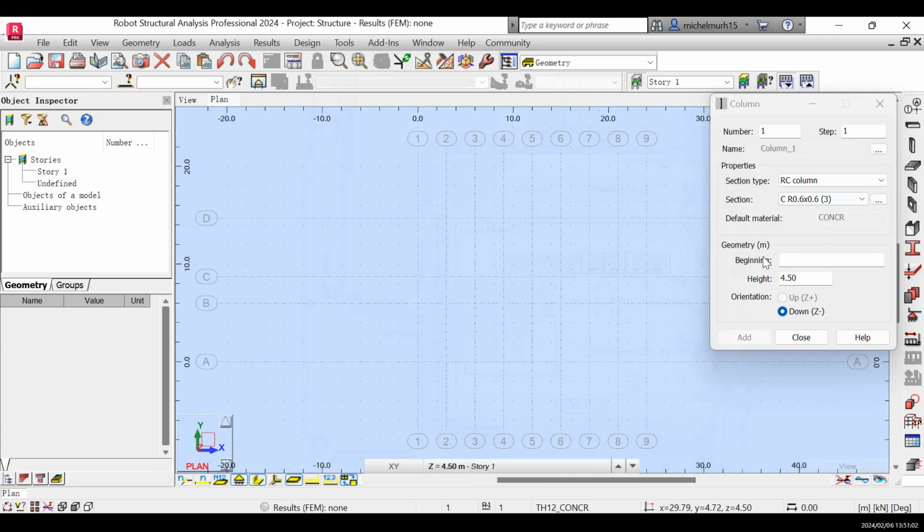So our column is supposed to be added at the intersection here for every line, each line here. So come here, make sure that the height starts from 4.5, and then put the mouse in here, at the beginning, and then press on the intersection, the first line only. I'm gonna show you how to make sure it's in the middle, right? Yeah. All right, until the end.